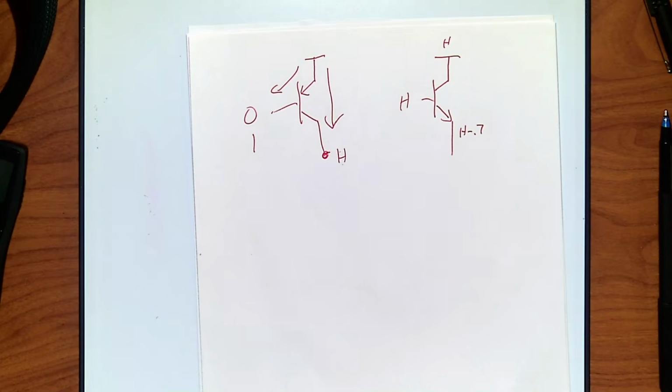Yes. And we care more about 0 because that reduces our noise. So we pick one, and it's better to have all the same type of transistor. But if you're trying to actually switch power, and you're doing this to drive a light or something, if you use all NPNs, and these are external power stuff, you will tend to lose a little bit. It's not as efficient, because it can't be. And that voltage drop has to happen inside there, so there's a little bit of heat and stuff like that.